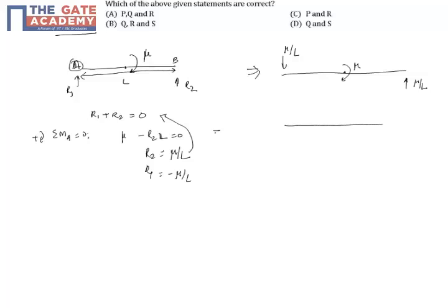Okay, now the shear force value, as usual we start from the right side. We take a section, and the right side of this section we balance it. Because the reaction is M by L in the upward direction, the shear force will be in the downward direction and it will be M by L. So downward we represent in the bottom. It again depends on your sign convention. So we represent shear force which is downward in the negative direction.